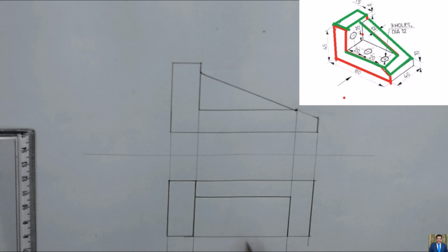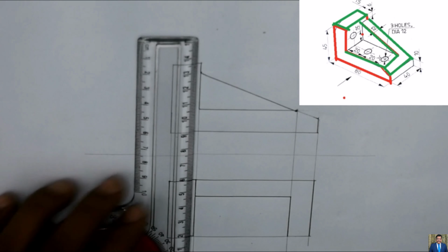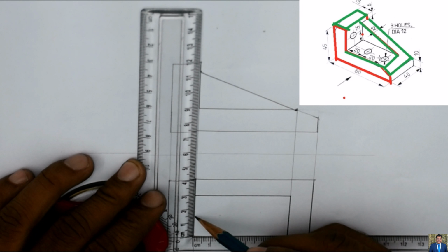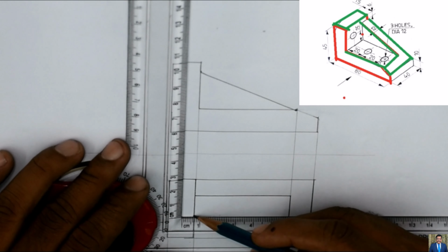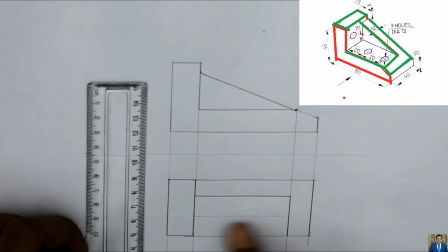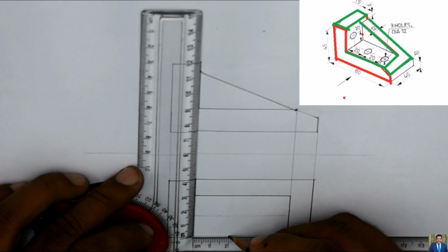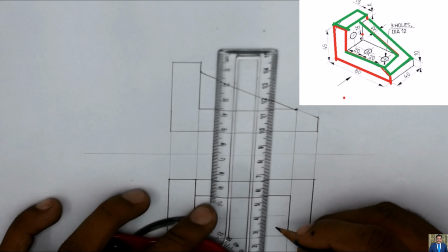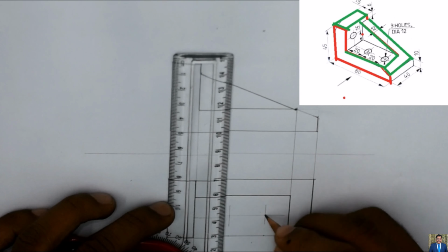And now we are also having some holes here, one hole, here one hole. So we need to draw them first. For drawing that, we need to take the distance, and the distance is given as 20 mm from this line. And I will assume that this is in the center. This is 28, so 14 mm. I'm just drawing this in between these two lines. I'm drawing one central line, and then after 20 mm, and again after 20 mm, I will draw these lines to get the center of this circle.